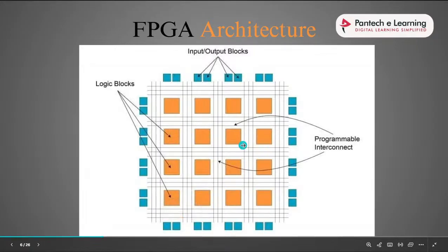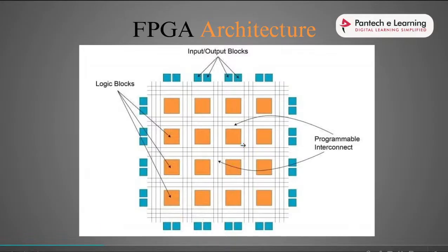Inside the FPGA, it has the CLBs. A CLB is a configurable logic block. It has some n number of transistors, and then we can configure that, so it can work by using the Verilog code. This is the main thing. Each and every CLB is connected with wires. You can see some lines here. These lines are used to connect the CLBs with the IOs.